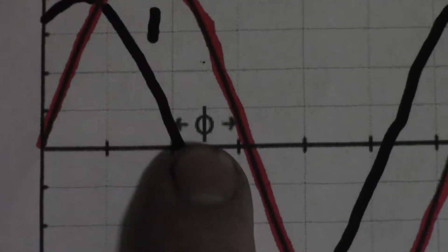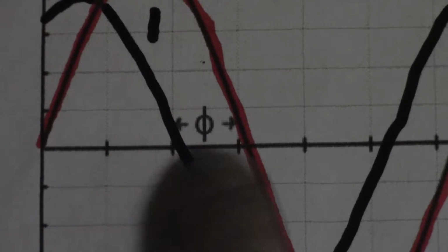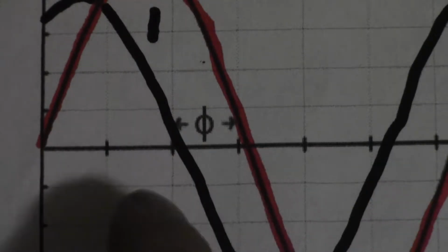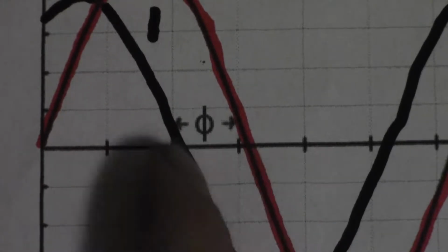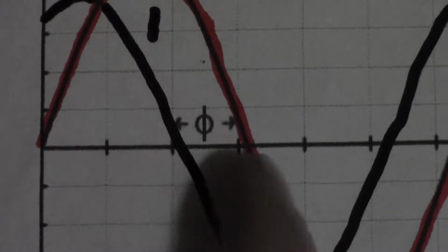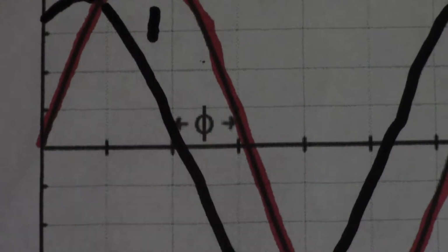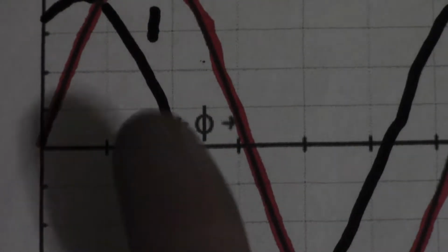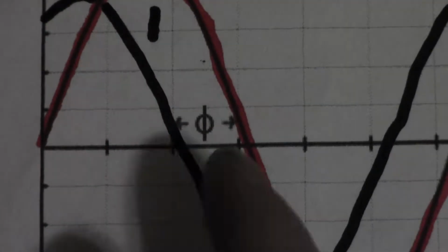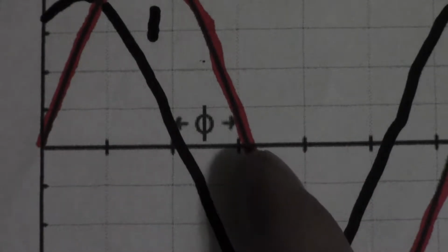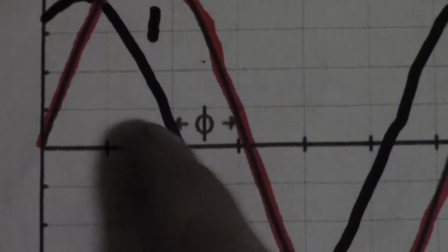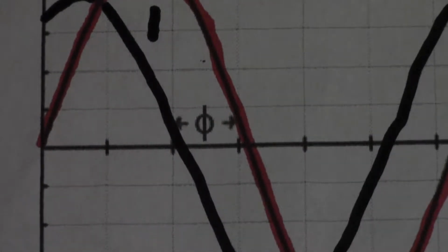You can see here, this is the symbol for power factor, and it gets complicated with the cosine of whomever while you calculate the distance between these two graphs. You find how far apart, how far out of phase these two are. You don't necessarily need to know that math. All you need to know is this symbol means power factor, and 1 means the power factor is ideal, and less than 1 in either direction indicates a slightly poorer power factor. That's all you really need to know.